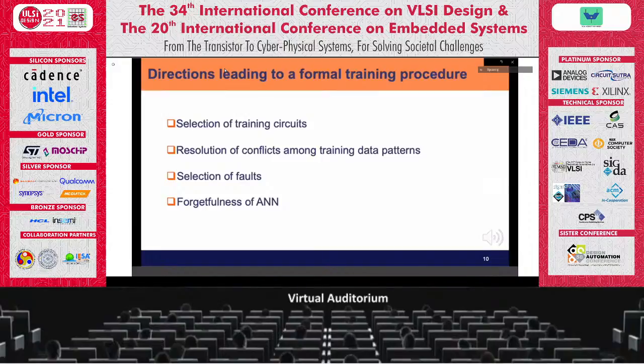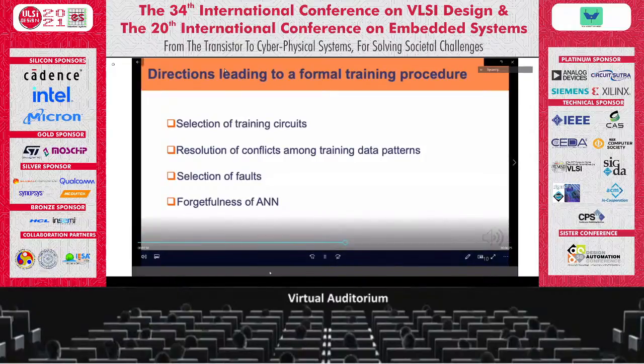That is, the training error of the ANN must be kept low by adjusting the number of hidden neurons. The fault must be accepted only if guidance from the resulting ANN reduces backtracks, and the faults used for training data generation should not be restricted to hard-to-detect faults. In fact, a fault provides useful training data as long as it reduces backtracks. And finally, the ANN may enter a zone called catastrophic forgetting when it forgets information contained in a large training data volume. Such consideration in training improvement is worth exploring in the future.